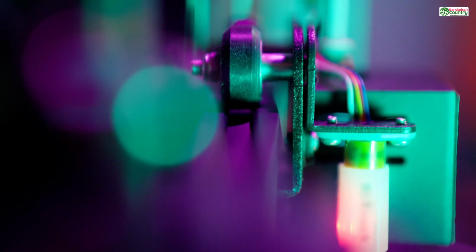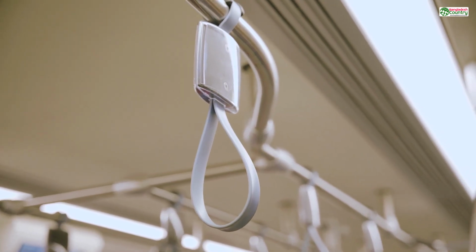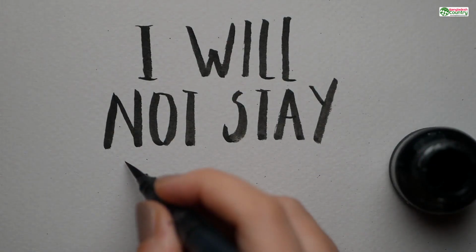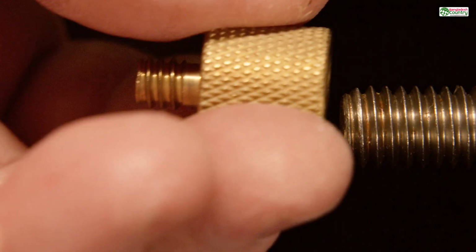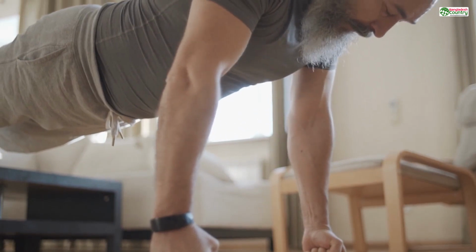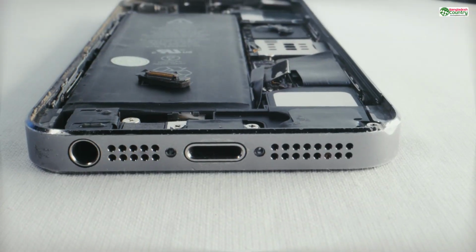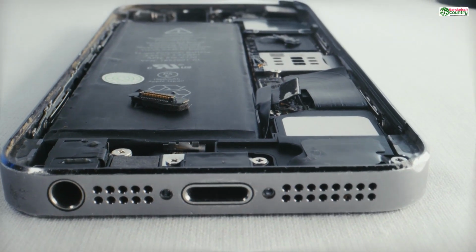Now, what if you're printing something that needs to be truly strong? A part that will be under constant load, like a component for a drone, a C-clamp, or a replacement gear. This is where you push into the 50 to 75% range. At this density, the internal structure becomes a dominant feature of the part, creating a powerful, reinforced object that can withstand significant forces. So what about 100%?